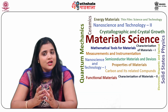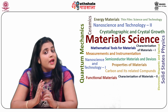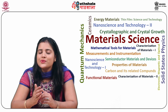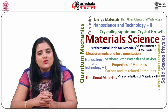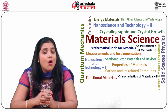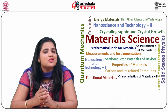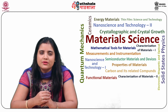Using the current IC fabrication technology, it becomes very difficult to produce resistors of values over a wide range that maintains an accurate ratio, especially with change in temperature. Also, being precision resistors, they add a lot to the expense and are thus not preferred.